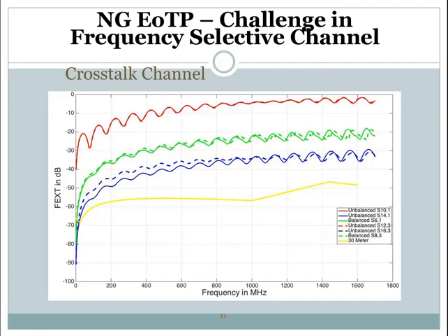So now we come to two very interesting observations. The first one is the frequency selectivity in the channel condition, which means the crosstalk and insertion loss are different on different frequencies along the cable. And the other one is that the short cables have very good insertion loss, but they also have very strong crosstalk. So the performance of the short cable is yet to be evaluated. It's not necessarily much better than the long cable.